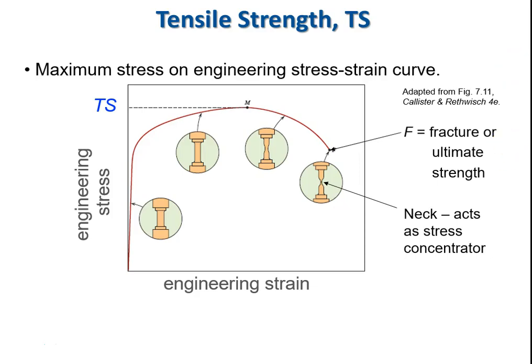In this case, not necessarily returning along a path parallel to the modulus, because there is no longer anything to return it. So in this case, the neck acts as a stress concentrator. This is very important, not so much for this chapter, but it will be very important for fracture, because the minute it forms, the area in that neck is no longer really being subjected to stress just from one direction. So it went from having stress just in, say, the vertical, the z direction.